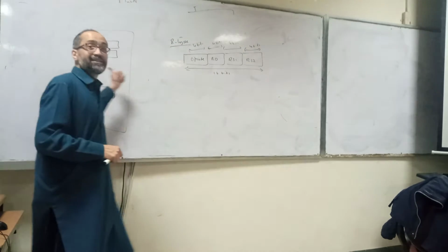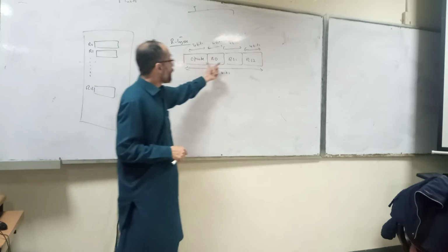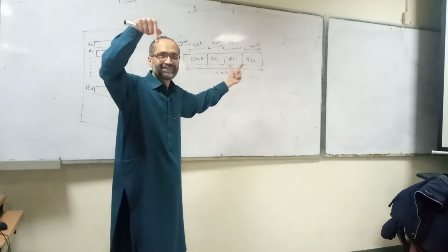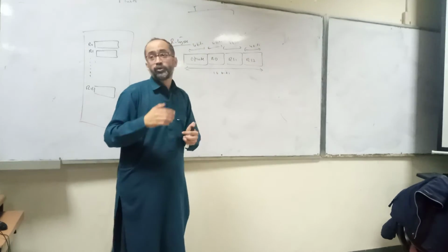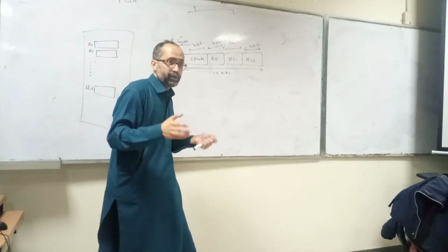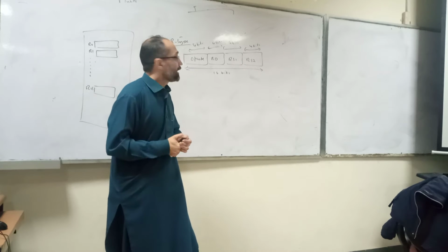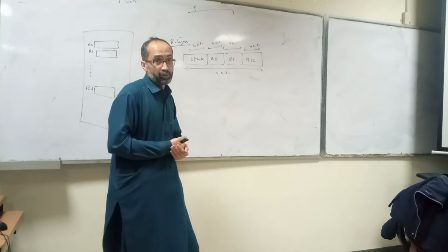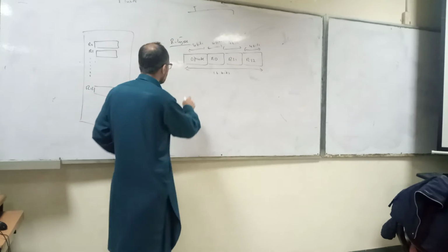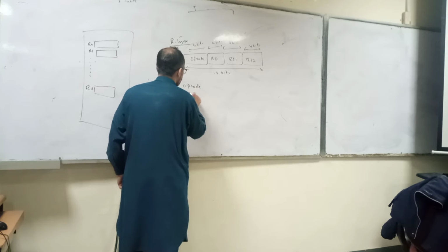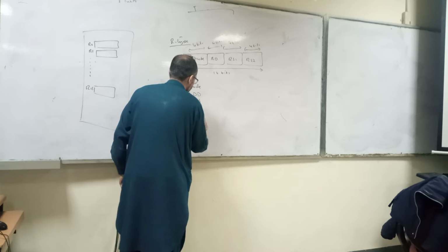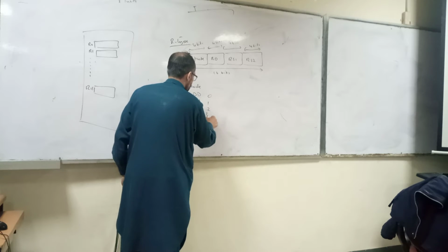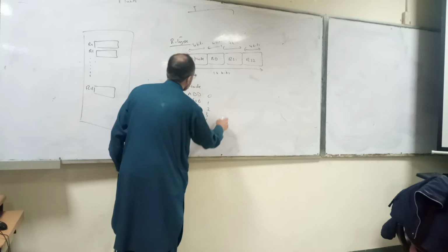Because the number of registers is 16, the number of bits required to identify an individual register is 4 bits. And we assume that we are using a reduced instruction set computer, our RISC architecture, and in this architecture we say that we are using register addressing mode. And for this opcode, let's assume that the microprocessor is supporting these instructions: add, subtract, multiply, divide, maybe logical shift left, logical shift right, and the opcode is 0, 1, 2, 3, 4, and so on, up to 7.